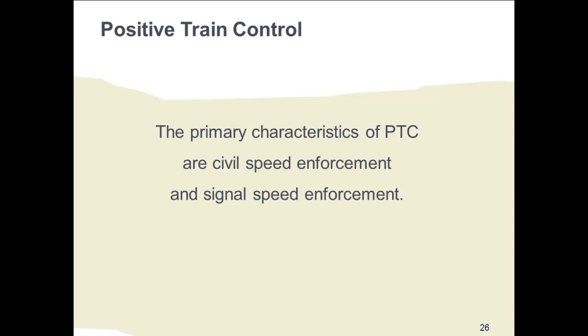With PTC in the route signaling world, the train engineer will no longer depend entirely for speed information from the employee's timetable. The signal system in the cab will tell the engineer to slow down to X many miles per hour. And if the train does not slow down, the positive train control system on the train will slow it down automatically. PTC requires a lot of computer programming. For each segment, it factors in the topography, the size of the turnout, train weight, braking efficiency, curve sizes, etc.